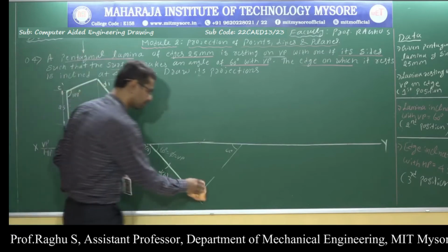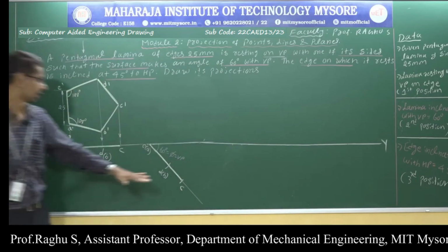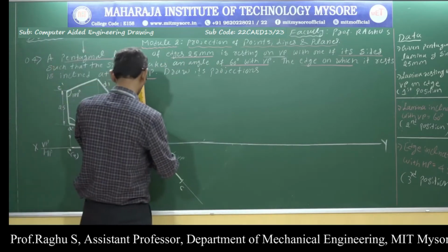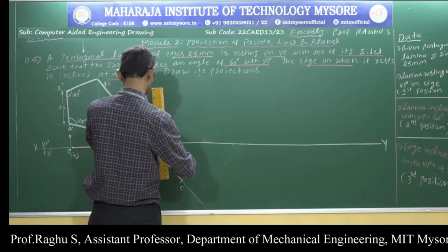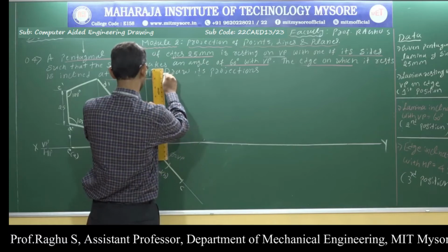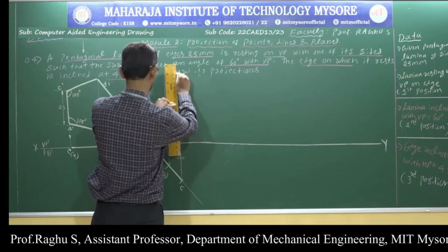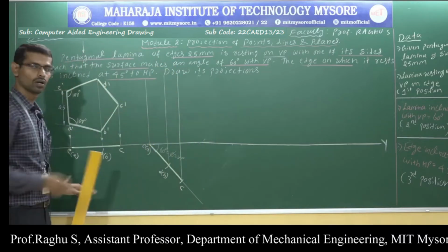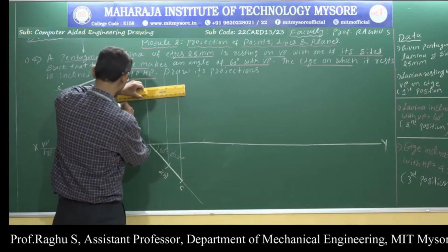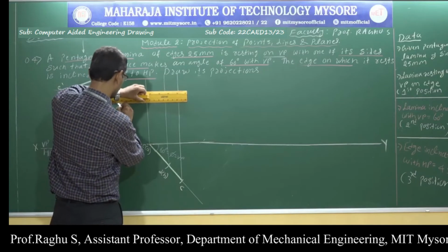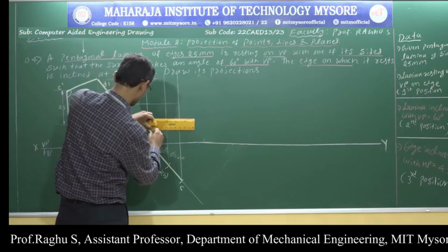Next, to get the second position front view, just draw upward projections. Projection lines are always thin lines. Just draw thin lines from all the corners. Next, draw horizontal projections from the first position front view.